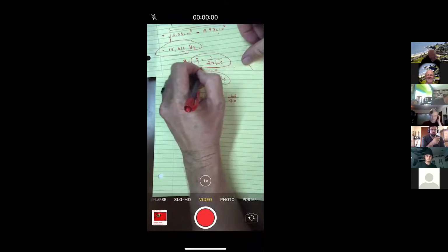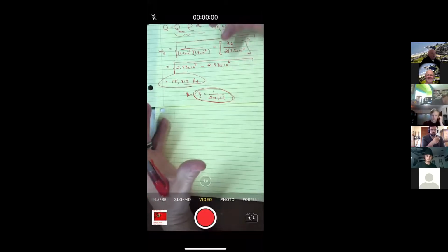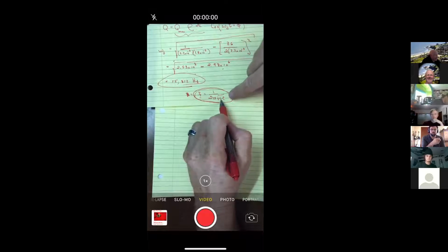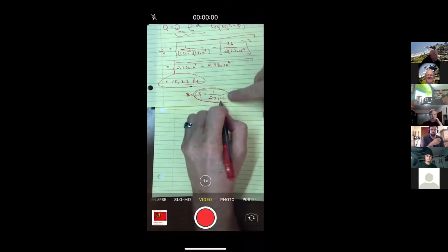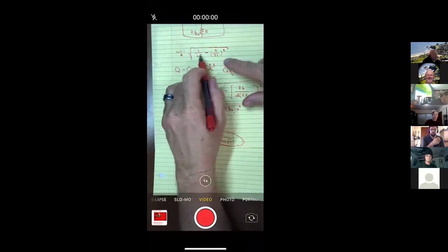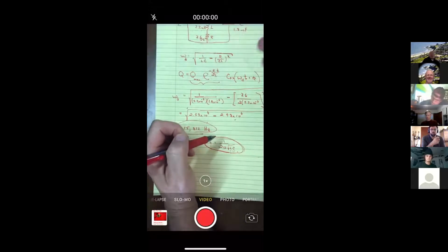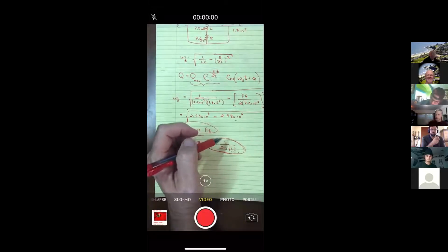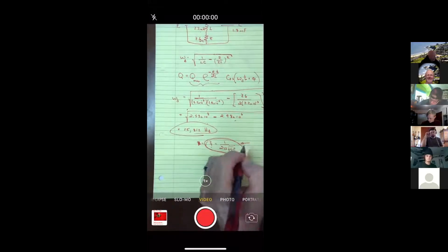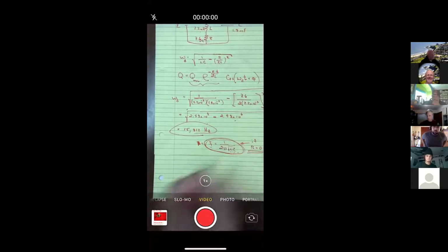So this is a great equation, but it's a combination of two equations, and if you're not careful, you may not notice that this 1 over the square root of LC is actually the simple case of an LCR circuit without any resistance. So it would not be appropriate for this question. This question clearly has a resistance. So this is only good if R equals 0.